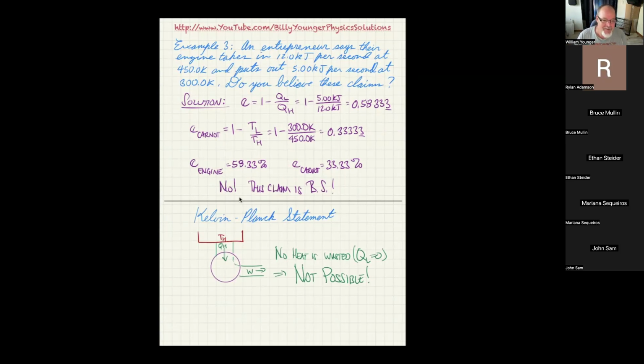So, anyways, that's another version of the second law of thermodynamics, which says no device is possible whose sole effect is to transform a given amount of heat completely into work. There's no way, once you've converted some amount of energy into heat, let's say 1,000 kilojoules, you cannot get 1,000 kilojoules back out, period. No way. Okay. That's just sort of the fundamental idea that heat is a lesser quality version of energy. So, any questions on that one?